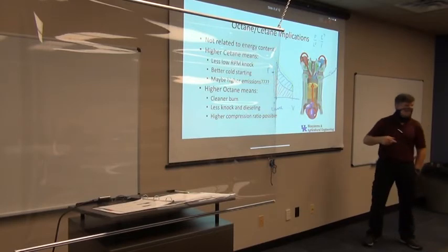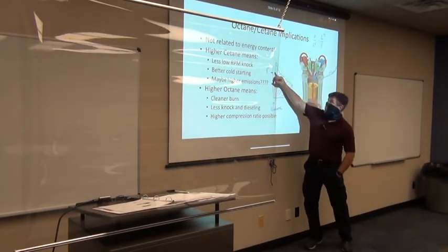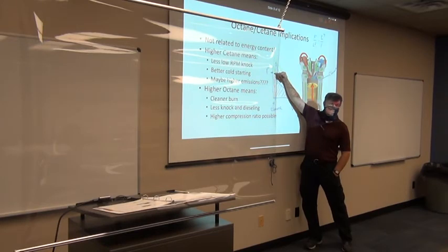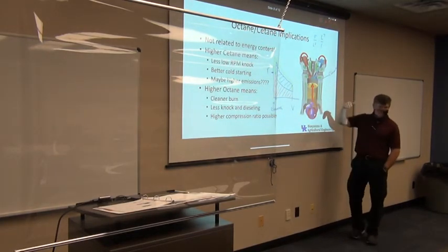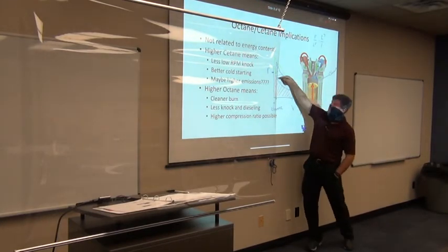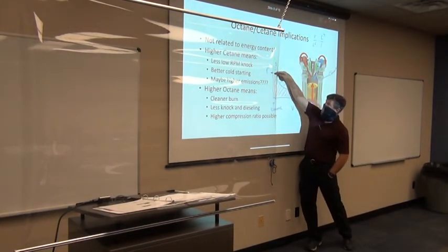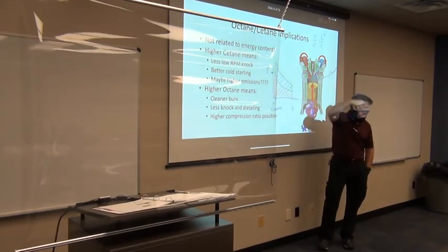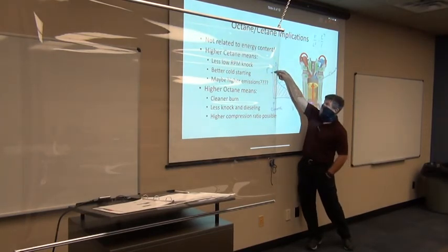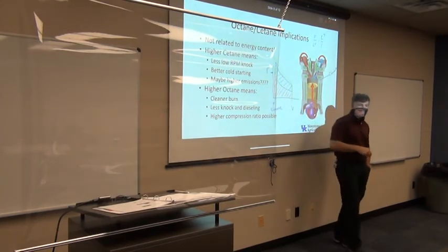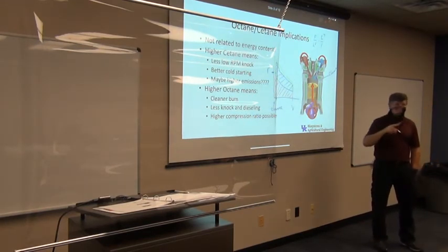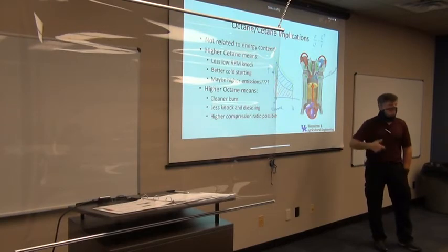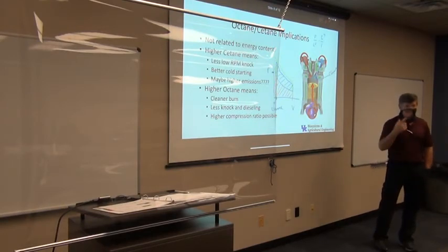Why does it keep running? Because this pressure is high enough that that engine was designed pretty close, and actually we did some modifications to them years ago and increased the compression ratio a little bit. So that auto ignition pressure is running really close. When an engine gets hot, PV equals nRT, like the gas law, the pressure gets up, and so that pressure is right above the auto ignition pressure. It's close enough that it doesn't really sound bad when it's running, but when you shut the spark off, there's still enough heat in that engine that it'll just keep on running. So it won't shut off.